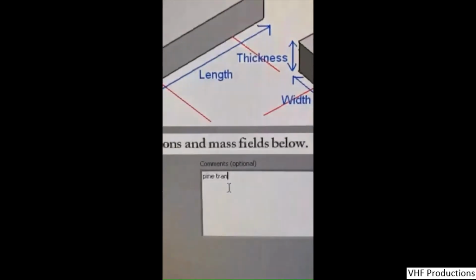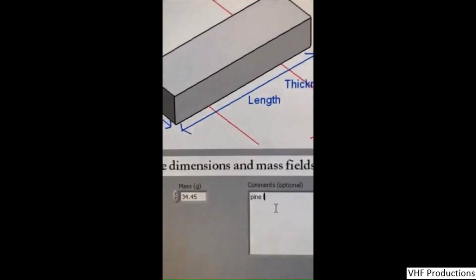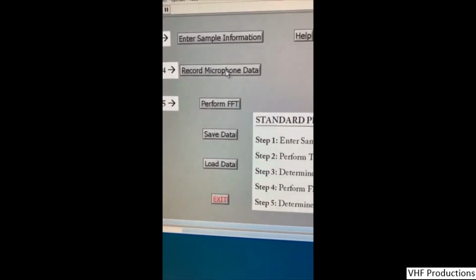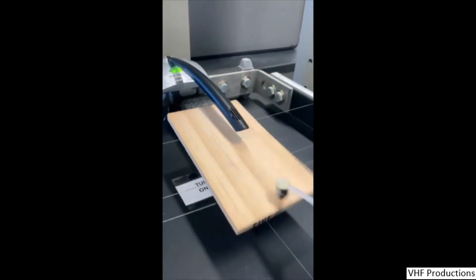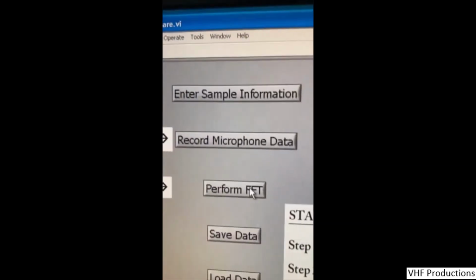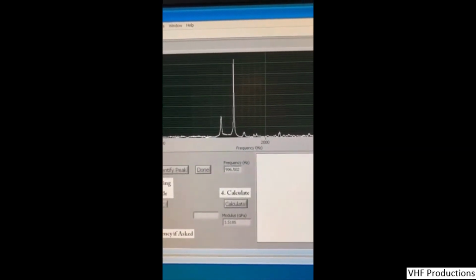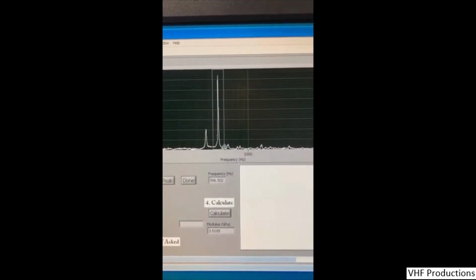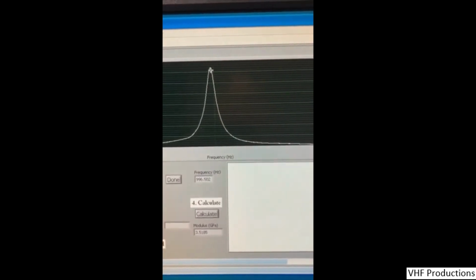After the acoustic signal is captured, the amplitude versus time signal is converted into an amplitude versus frequency signal, and that signal is then used to find the highest peak position of the amplitude of the peak in order to determine the resonant frequency associated with that highest point. Once the resonant frequency is determined, then the modulus of the plank can be determined.